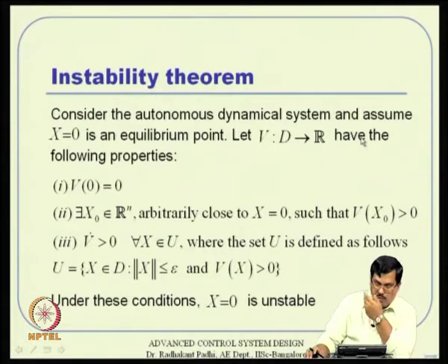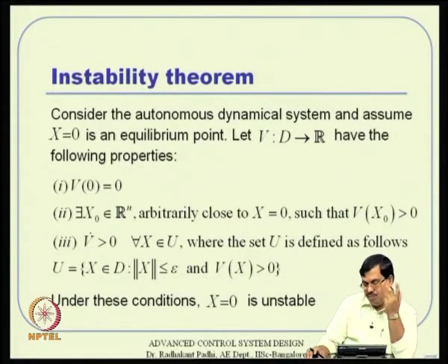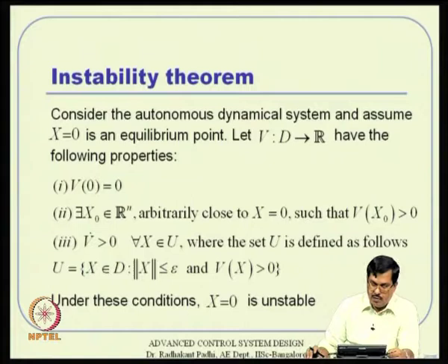Then on the way we discussed about instability theorem also, because all these Lyapunov theorems happen to be sufficiency conditions. So, we are never sure, if one selection fails, whether some other selection will succeed or not. Because of those difficulties, people have thought about instability theorems, in the sense that if the system is really unstable, no matter whatever attempt you do for selecting a good Lyapunov function, you will never succeed.